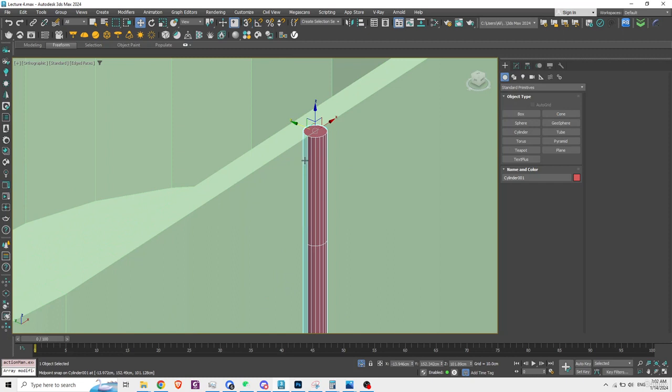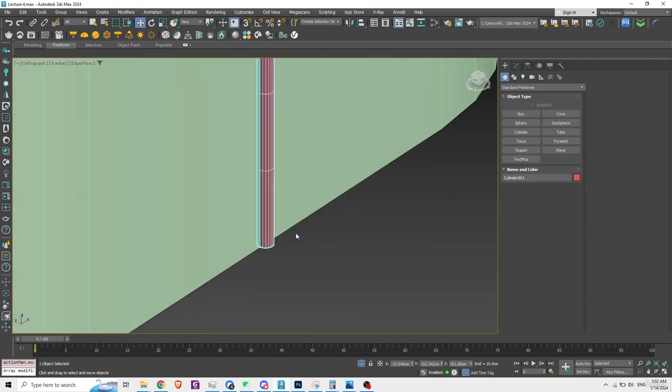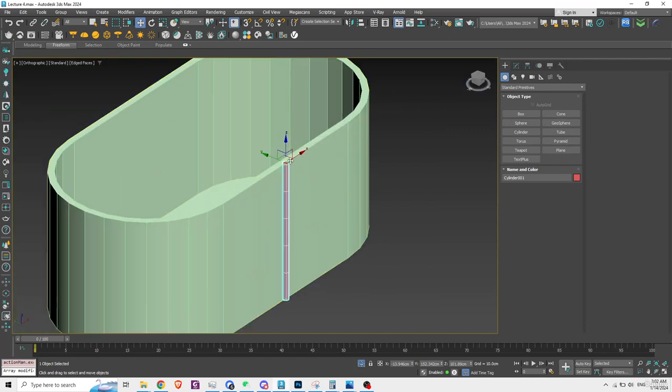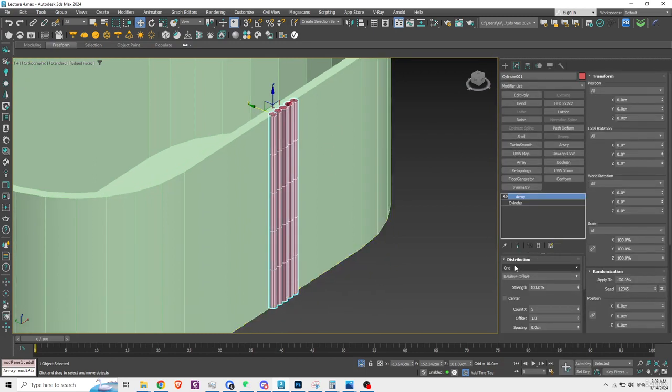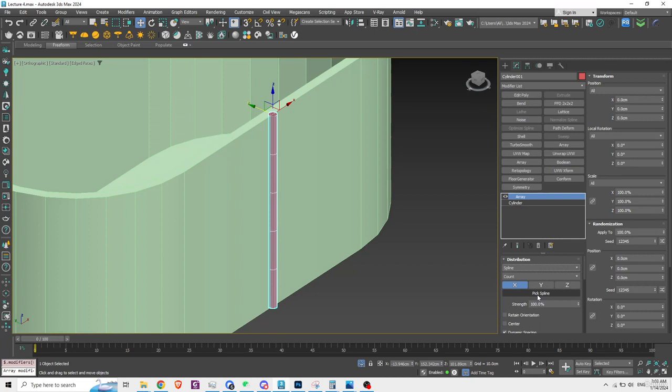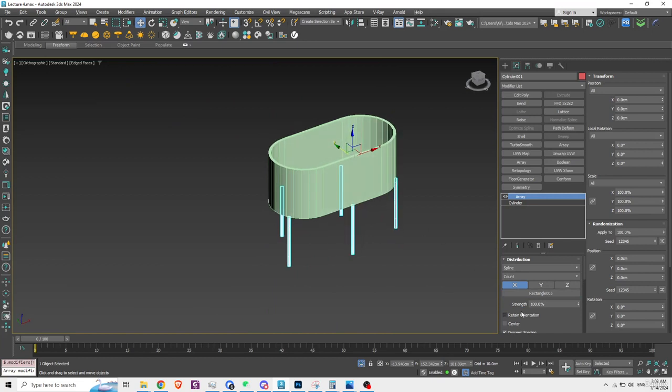play smart. And if you are using 2024 3ds Max, that is going to be very good, and it will make your life a lot easier actually. So I am going to apply array modifier, and in array distribution I'm going to select subline, and it will say pick subline. I will click on the subline I copied, and boom. Now I have to just add the numbers.